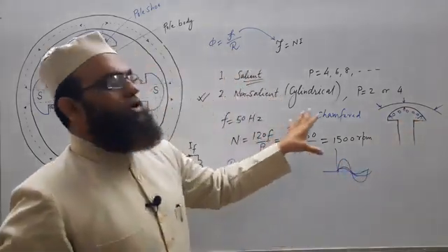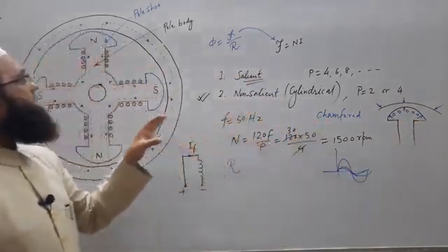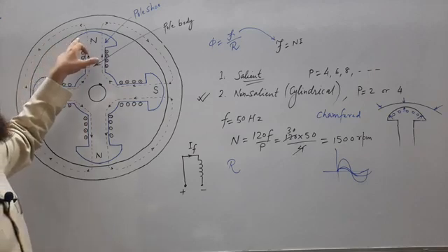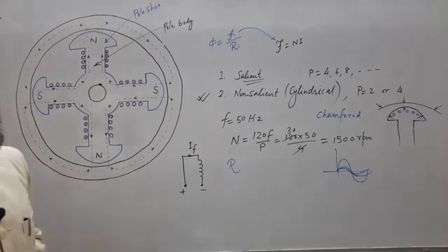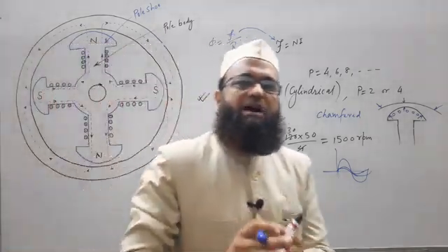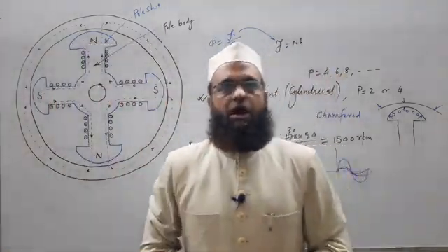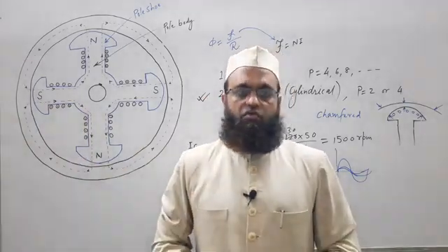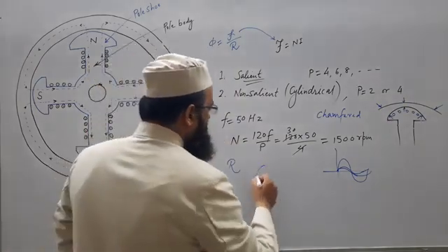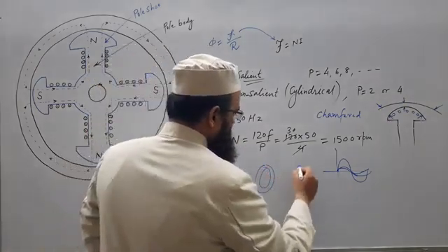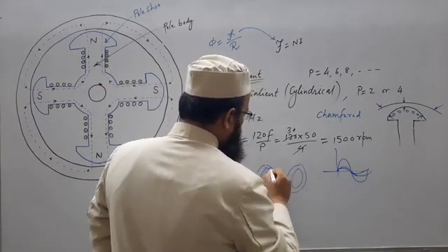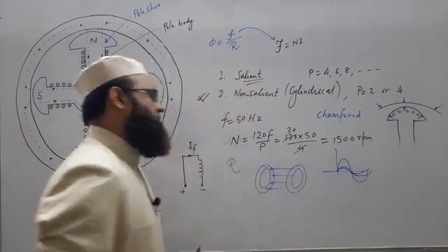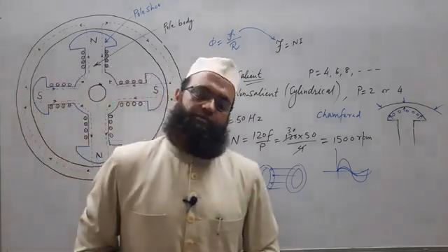So on each pole we have copper bars inserted on the pole shoes, and these copper bars are brought out together, connected at both the ends by end rings. So you will have a structure similar to that of a squirrel cage rotor of a 3-phase induction machine.